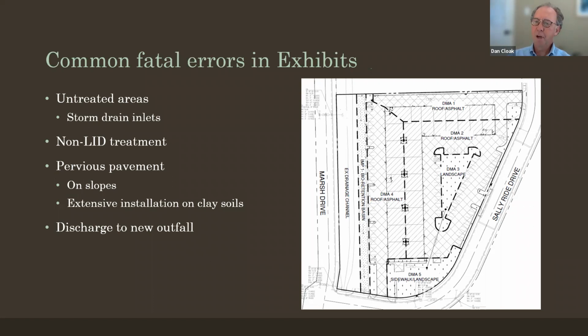If you have a storm drain inlet that's just there in the conventional way, like serving the pavement, you have to ask the question, where is that runoff going after it enters that storm drain? It could be that it is piped down a slope or a hill to a flat area where it was more convenient to locate a bioretention facility. But that situation is relatively rare. Typically, a storm drain inlet is definitely something to look at to see what's going on with it.